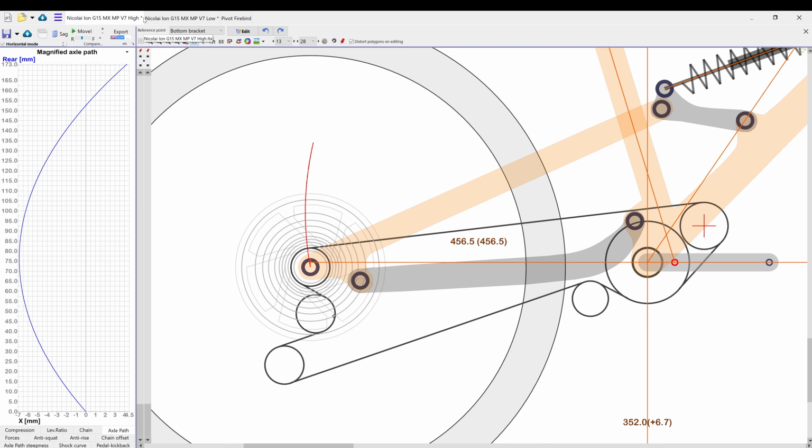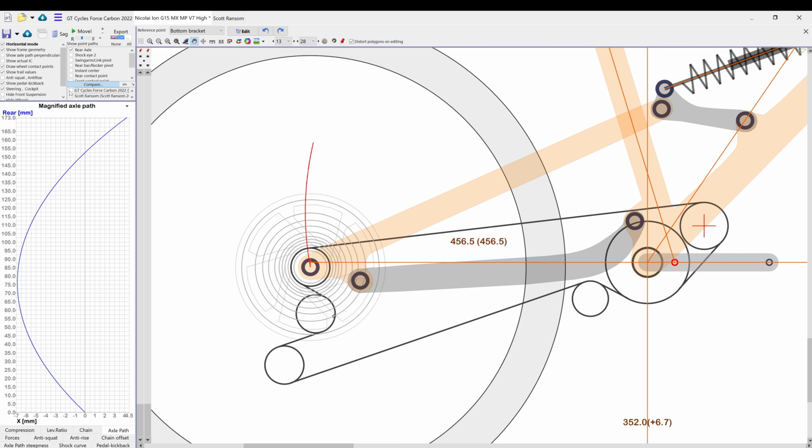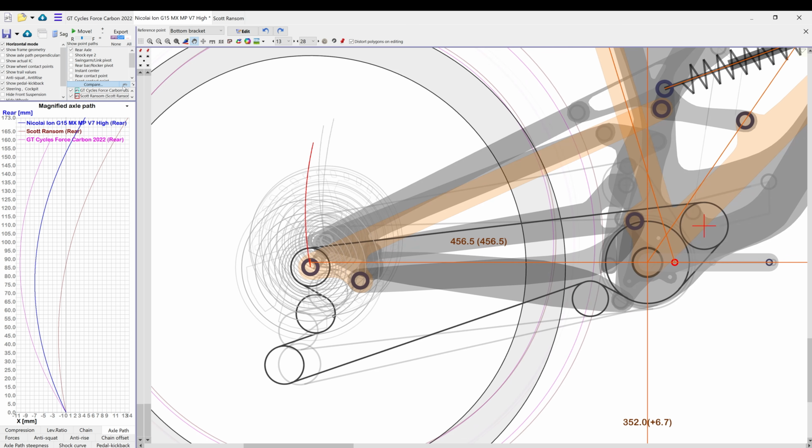Despite this, the new geometry has some noteworthy benefits. Rotating the mainframe back also rotates the axle path, making the axle trace a more rearward arc than stock. You could say this bike essentially becomes a mid-pivot, with the axle path sitting somewhere between a standard low pivot and a high pivot one.